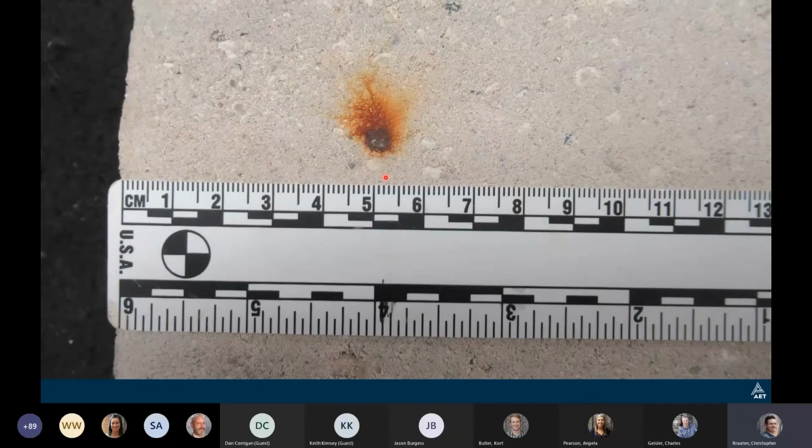I think it was placed at somebody's home, and the owner noticed that ugly stain, so they had them send it back, and they came and replaced it, and they sent it to us and wanted to know why. So we did a saw cut right through it, to see if we could try and save some of that particle. And we have run into this before. It ended up being a pyrite particle, and it's kind of an interesting pyrite particle because it's not just straight up pyrite. It's pyrite made of like millions of little tiny pyrites. And so the client sent their quality control people into their pit, and they started looking for these dark particles. We just said they'd probably be dark particles. They started collecting these dark particles and separated them before they went into their mix, and they sent them to us. So we got to look at them,